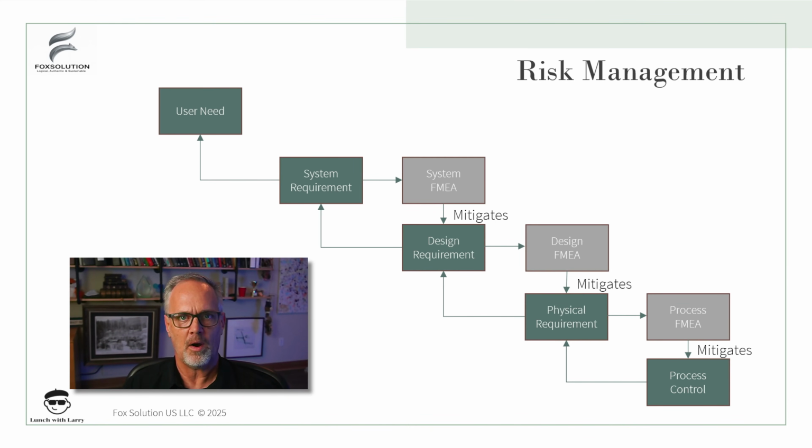So if we have a design requirement that is maybe something like, in a sterile barrier bag, the design requirement is the sterile barrier won't migrate harmful bacteria. And some of the physical requirements might be you want to use Tyvek, or you might have a 3/8 inch bag seal. And those are critical dimensions and/or characteristics of the design that are necessary to assure that that bag doesn't migrate the harmful bacteria. So in the design FMEA, we're going through from a mechanical design standpoint now, because we know what component that requirement is deployed in. I can go through from a design standpoint and define everything that's required to be in the design to give me that migration remediation.